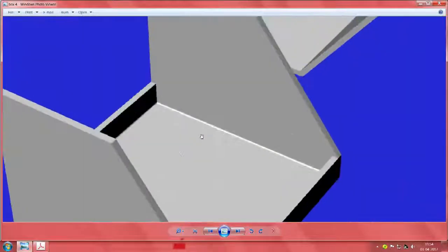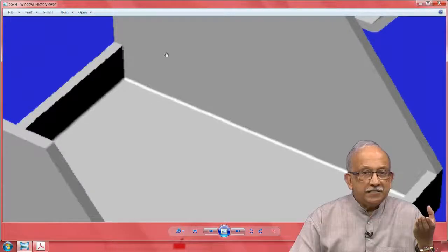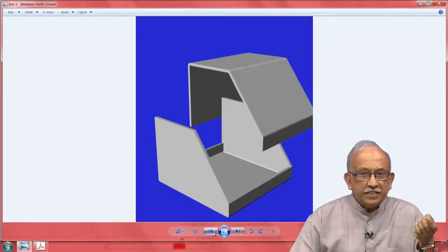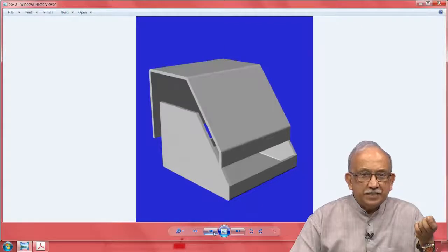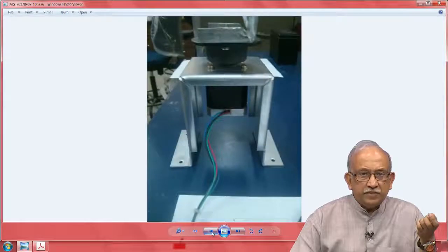neatly done enclosure. But here again you notice, we talked about spring back. So when you want that spring back, this U needs to bend in a little so that it can come out, and in this corner you need a small gap to ensure that the bending takes place without any problem. Understood, no? So in the corner a small notch is required. Usually these are all details which are to be done by the fabricator, but it is still useful for you if you can follow these things.